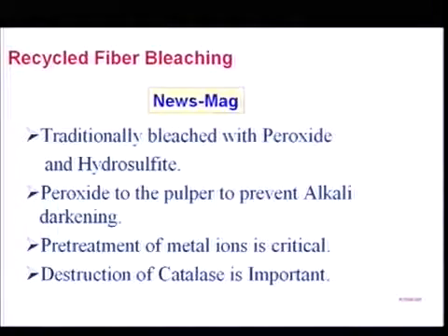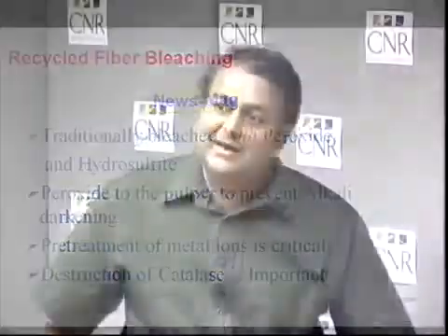And in the case of the news magazine, when you recycle, you need to watch out for catalase enzyme. It's present in the white water. If white water temperature is low, this catalase can go back. When the white water is going back as a pulper dilution water, this catalase can attack and take away your peroxide. You keep on adding peroxide, it does not help you with brightness because it gets decomposed to water and oxygen because of the catalase present.